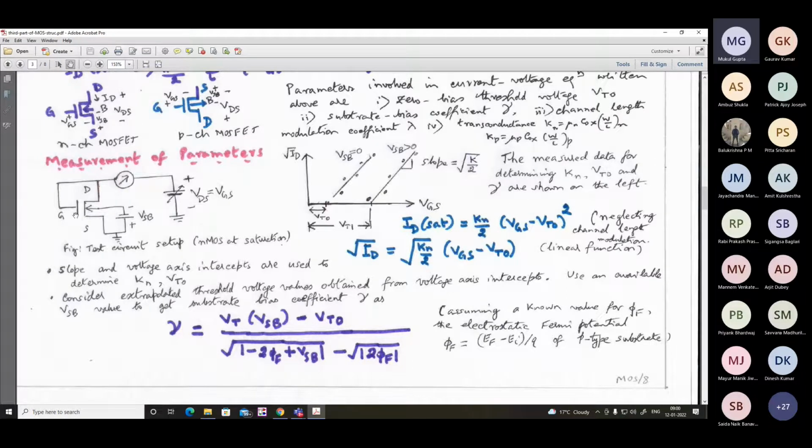See, once again, gate and drain are shorted. That means you will force the transistor to be always in saturation. That is one thing. And next, what is your question? What is the problem in biasing? Like you told, in this circuit the source is grounded and the body is connected to a negative potential. Yes. Actually, the problem is that in general, for all NMOS transistors, the body or substrate is grounded, not the source. Right.